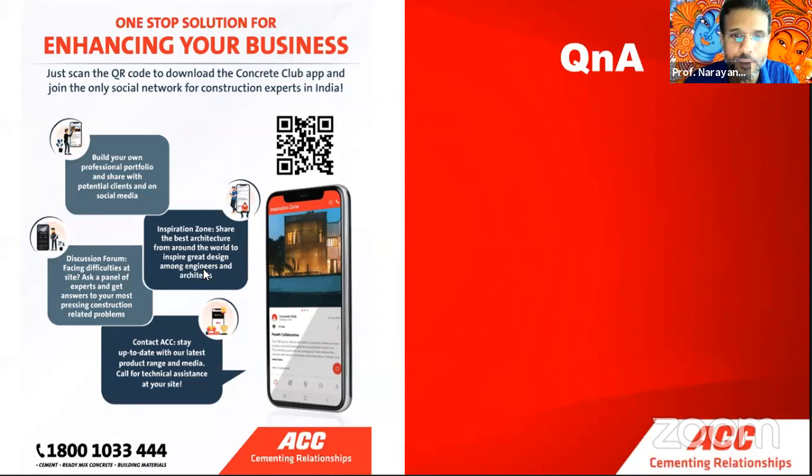Is it possible to use brick waste to produce UHPC? Maybe if you crush bricks so nicely and make it a fine ground powder, you might be able to. But for a material that has to give you 150 megapascal, I wouldn't take that risk.